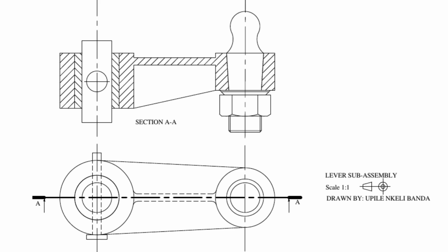If the saw passed through a hollow hole, we leave that area blank. Here is an example of sectioning. The cutting plane R on the top view of the lever subassembly has instructed us to cut it there and show the inside in the front elevation.